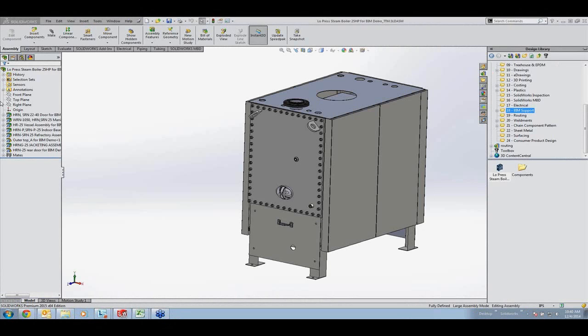All right, I have 2 bodies here, so I'm going to go ahead and hide that top body there. I've prepared a sketch here to cut with. Now you might notice that this cut has an open profile on it. Before, you'd have to do a sweep feature, but now there's an option to use selected contours. Contours were available for extrudes and cut extrudes in the past, but now I can use it with the edges of my faces here. So there's a circular edge there. I can select that as a contour and create my cut.